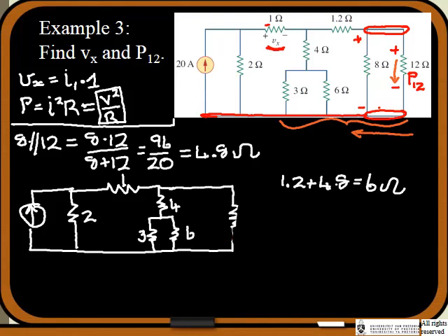There we go. So that then gets even simplified further, and we're left with a 6 ohm resistor, which is now the combination of the 1.2 plus the 4.8. What's next? Right, there's nothing else in series with a 6 ohm resistor. Next, I'm going to put my sights on these 3 resistors. So how are they combined?